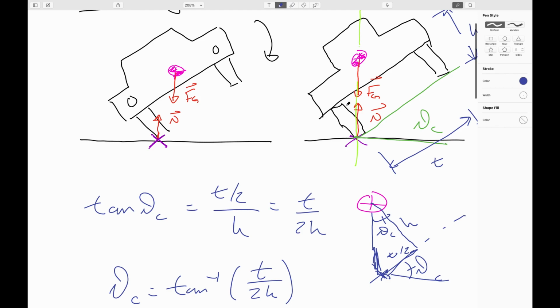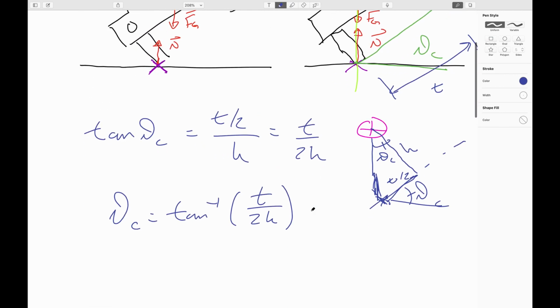The battery pack is typically over half the weight of the car, and by doing that, you can have the center of gravity of a vehicle be maybe 18 inches off the ground, something like that. You can have quite a low center of gravity, just taking advantage of the fact that these battery packs are incredibly massive. So if you put it as low as you can in the car, at least one way to make lemonade out of the lemons is that it makes it incredibly hard to flip the car over.